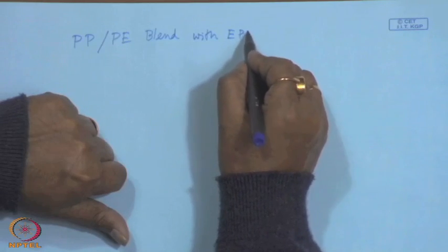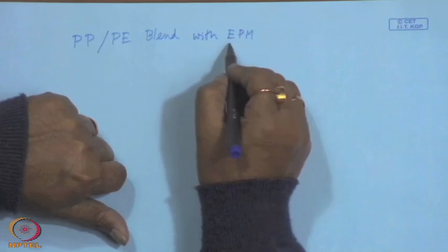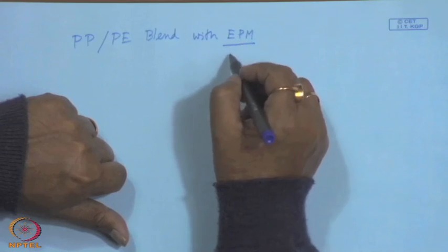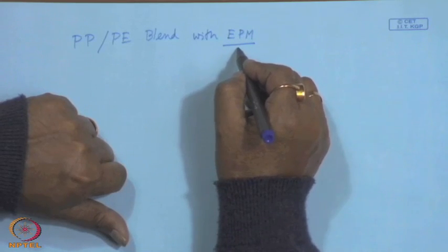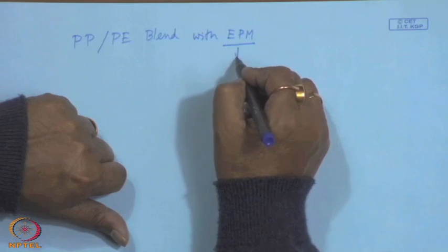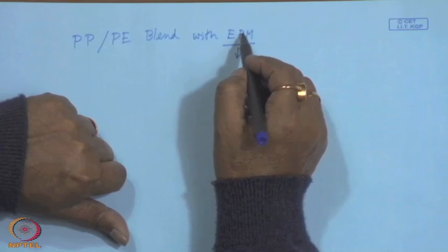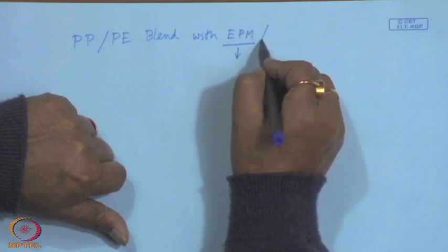This is a purely saturated rubber without having any cross linking site. To make it cross linkable, one should use some free radical cross linker to cross link it. This is also an elastomer, ethylene propylene copolymer, or one can take EPDM.